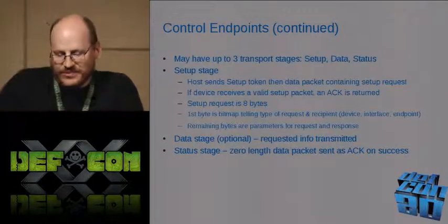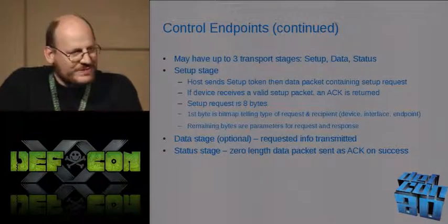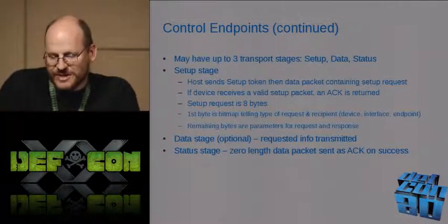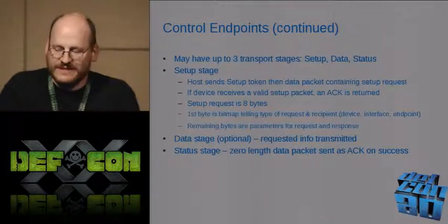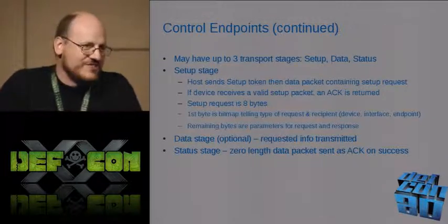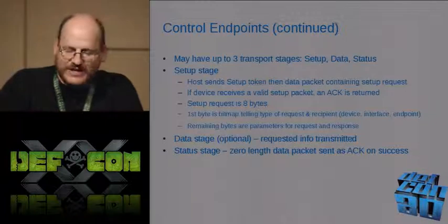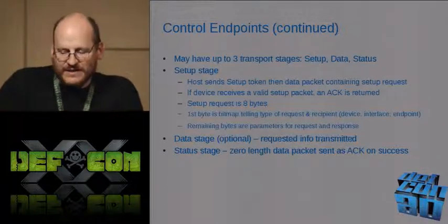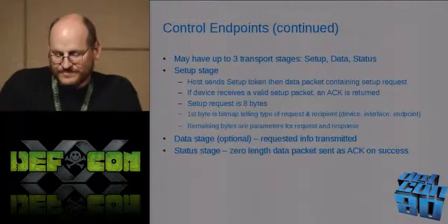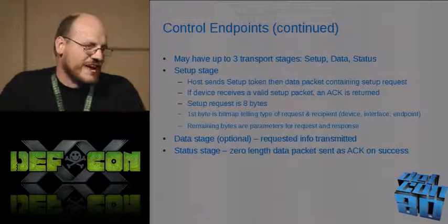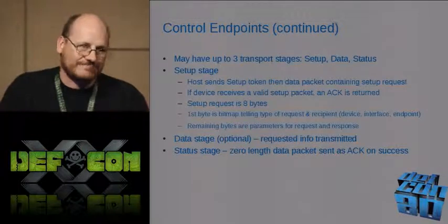All right, control endpoints. You get 3 stages in a control endpoint transfer. You have a setup stage, maybe a data stage, depending on the kind of communication, and then a status stage. For the status stage, you just send a zero-length packet back that says, ACK. Yeah, we're all good.